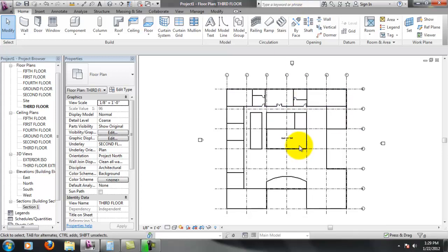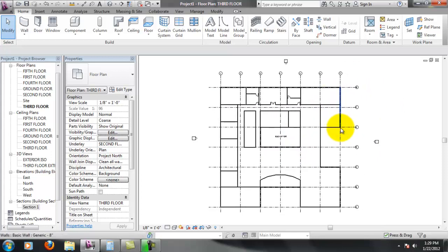So I guess the first thing that we need to create in order to do some of these calculations that I'm talking about would be an area plan. And then there's different types of area plans. The area plan we're really concerned about is the total area, rentable area of the space. And all of the calculations that I've done here or will be doing here will be based off of the IBC 2006 code. I don't have the up-to-date code here with me, so all the numbers that I'm pulling, just be aware that those are from the 2006, and I don't imagine that they've changed much since. However, it's always good to double check those numbers to the new code.